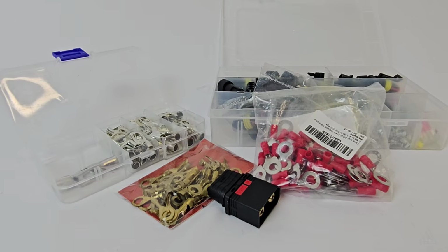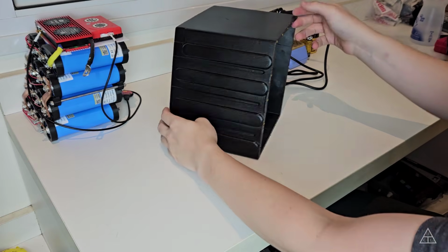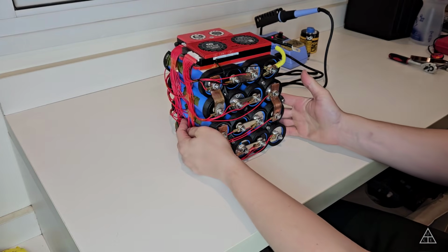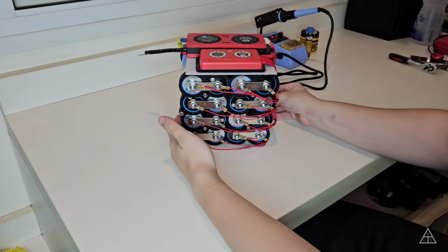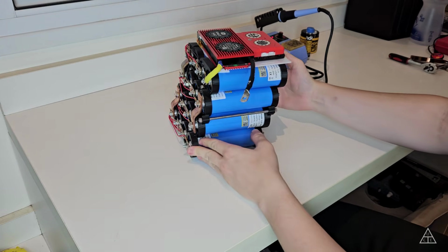You will also need a couple of connectors that you must decide which ones are better for your application. The enclosure of your battery pack also may vary. The one that I built for myself needed to be 3D printed because of the geometry of it. For putting everything together, a good rule of thumb is to follow the BMS manufacturer's orientation. Usually BMSs come with a manual of instructions on how to do it.